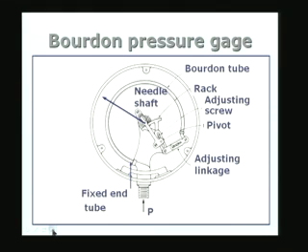So, with this background, let us look at, for example, the calibration of a pressure gauge of the type which is indicated here. So, what is calibration? Calibration is, in this case, the pointer is going to occupy an angular position, and each angular position corresponds to a certain pressure difference between the inside and the outside. And I would like to make a scale on the circumference of this circle, indicating the position of the pointer, and corresponding to each position of the pointer, a pressure reading must be indicated. So, that is what we call a calibration exercise.